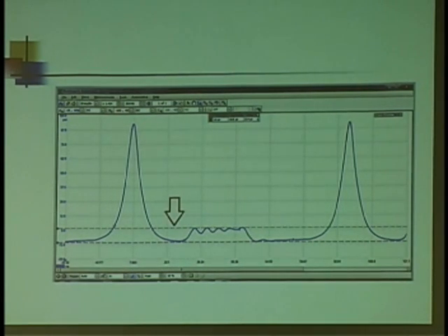Now I'm going to move down to the exhaust pocket. I'm coming down from TDC towards BDC on the power stroke. And what happens just before BDC? The exhaust valve begins to open. Look very carefully here at this part of the pattern. Notice how it's nice and smooth, and all of a sudden that changes right there. See how it abruptly starts to rise? That's when the exhaust valve opened. If you see this nice and smooth, just nice and round, then you've got a problem with the exhaust valve.